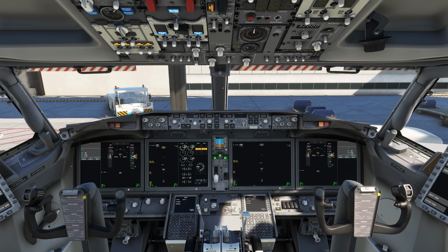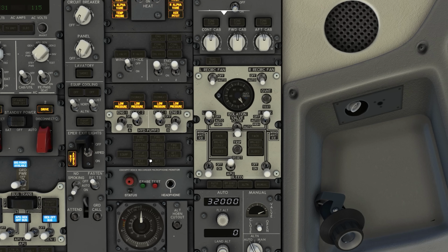So for example, if we do a bleeds off takeoff, there's a new bleed light which illuminates if we forget to reconfigure the aircraft. So here's the aforementioned light. As we can test them here, you have 2 bleed lights. Previously they were called bleed trip off in the NG, and these lights have several different meanings as well. They can illuminate if you have the bleed trip off due to excessive bleed air or pressure or under pressure or temperature, a failure with the bleed air system, or incorrect configuration, as I just mentioned. This wasn't available in the NG.